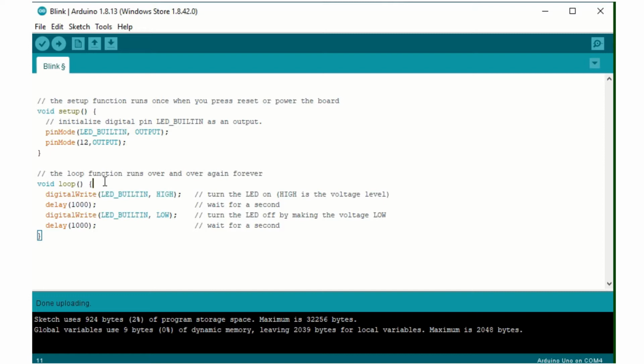So what happens on the first line of the loop? Okay, so we've got digitalWrite, LED_BUILTIN, HIGH. And by the looks of the explanation, that turns on the LED at a high setting, so the voltage level is high. We're up at the 5 volts there from our earlier discussion. So we want one LED on at a time, so we want the other LED off now. When the blue one's high, we want the white one low.